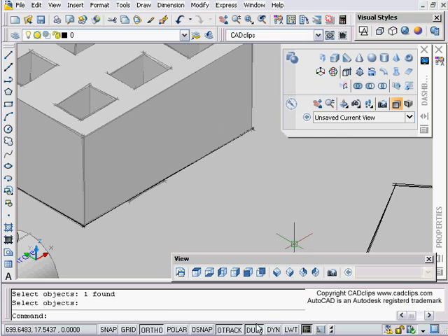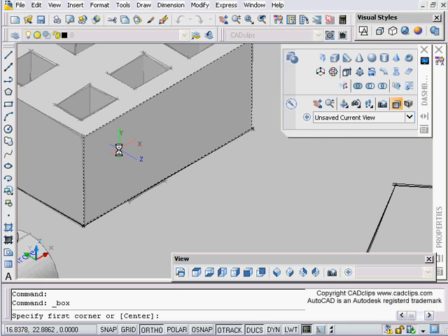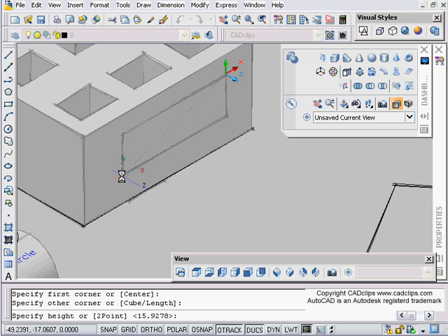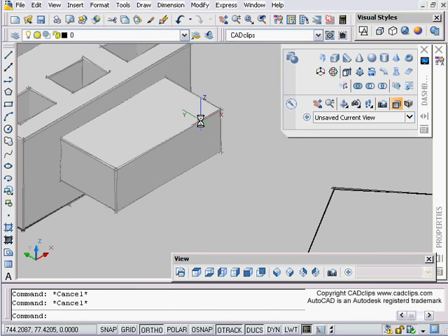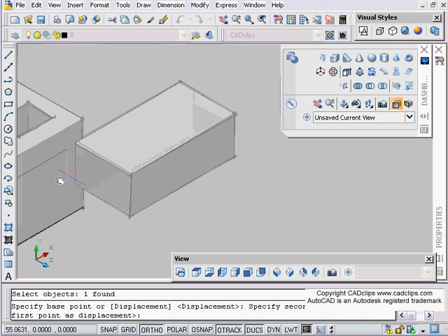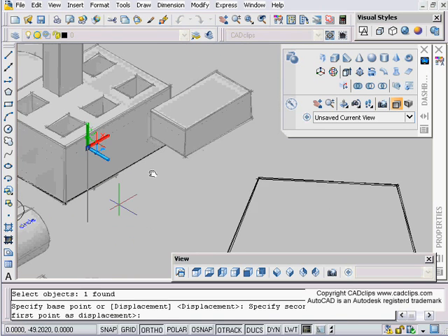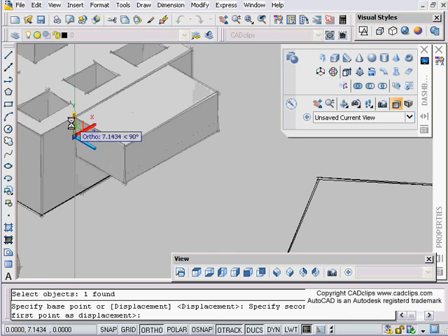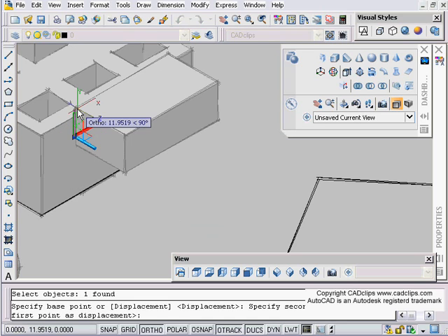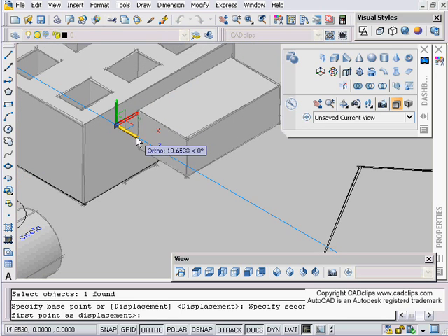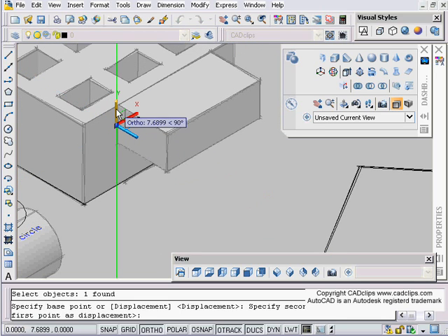Okay, let me do that one more time for you. Using my dynamic UCS and the box, hover over here, make sure you're getting on the right plane. You can see the outline, and sometimes it's easier to change your visual style. Pick, and then pull. This, when I go to do my 3D move, enter, pick, is a separate object, is all I'm saying. So when you do your push-pull off of a surface, it creates the new object as part of the original object of the surface it was dragged on. So maybe do a repeat of that exercise.